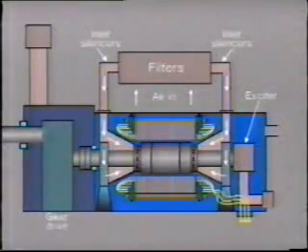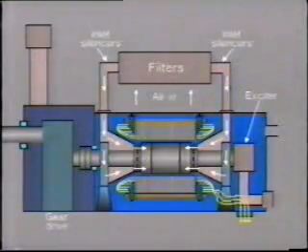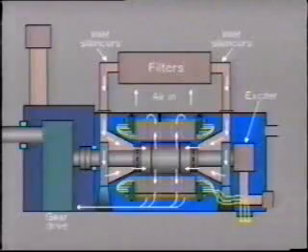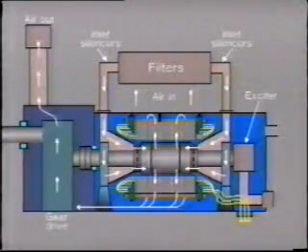The air is then drawn down through silencers into the fan impeller at each end. The air is then exhausted radially from each fan under pressure, and this is directed to follow the desired cooling path, eventually exhausting to atmosphere via the gear drive in this particular unit.